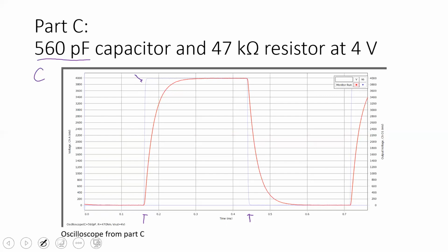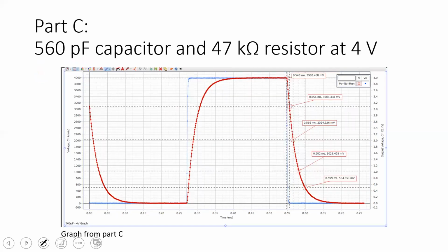So here, everything is set up as described in the lab, and we've measured our charging and discharging. Remember, our equations that we have in the lab are for this discharging section. Again, I've taken these measurements: our last time at the maximum value, our time at half the value, 1/4, 1/8 of the max value. So again, we're going to test out, does our prediction for the half-life match with our experimental values?